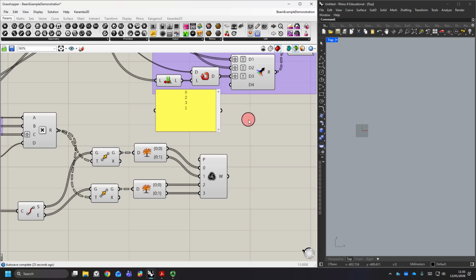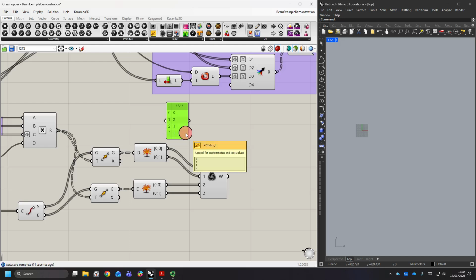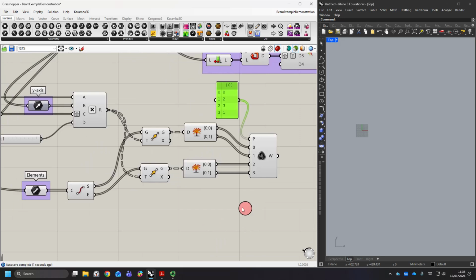So that's effectively the first number in the explanation that I showed previously. Change that into multi-line data, and you can see just in here, this is the order that they're actually going to appear in after the weave component. So we'll just do that.